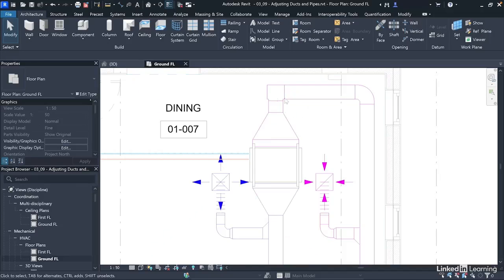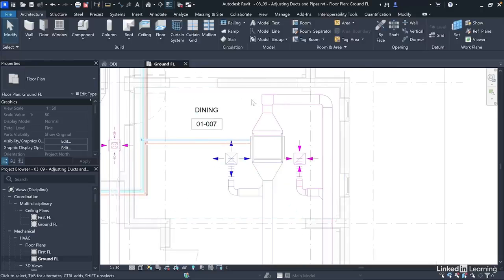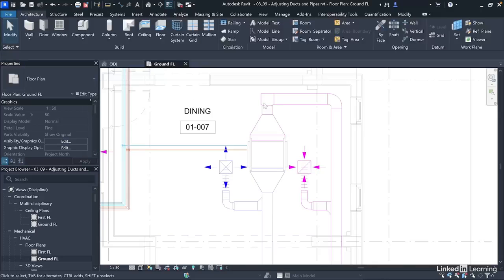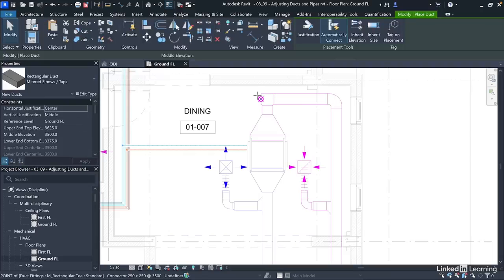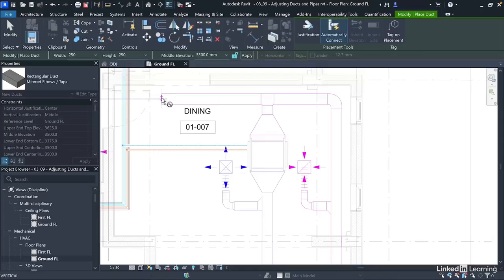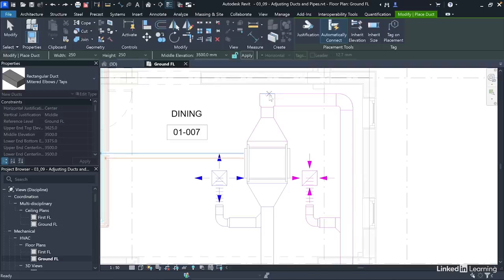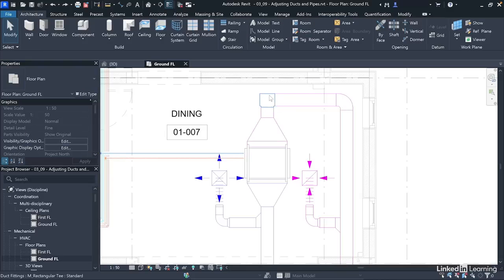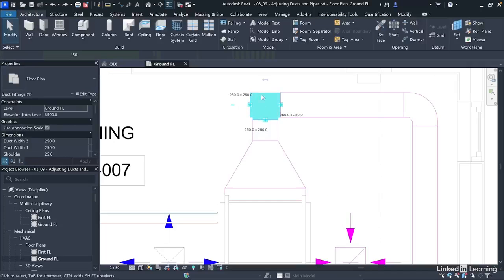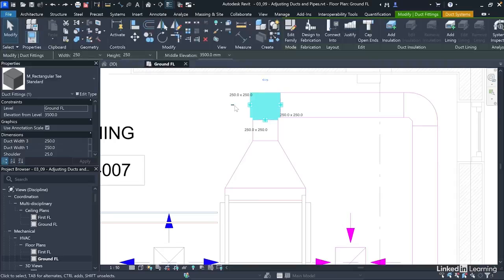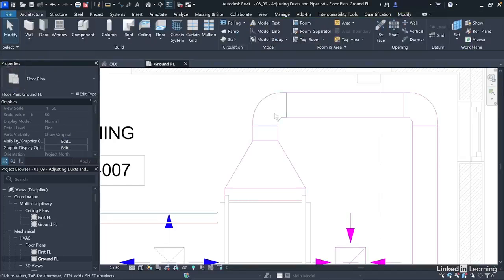So let's say, for example, I have another air terminal here and I want this duct to run there. I can change it to a T and then I simply create similar and I run another duct to continue running the layout. So if I want to undo this, I can just click on this existing T, or let's say I have a T, I want to change to an elbow, I can just click on minus. Now I can see flip. So the icons change a bit depending on the scenario and the fittings that you have in place.